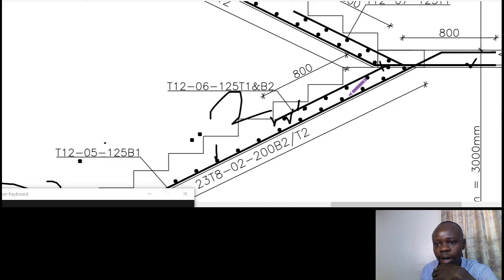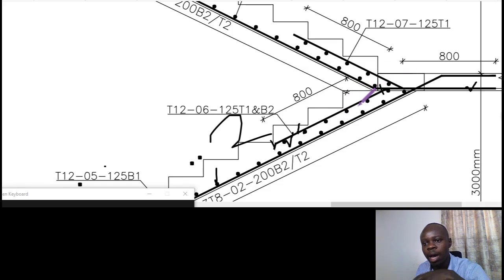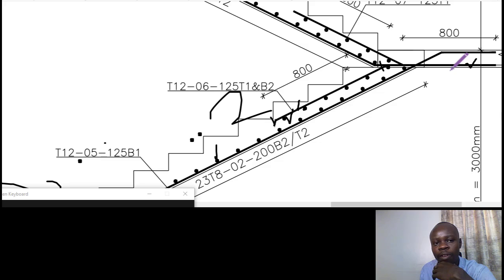You know that we have it like this now to the slab. Actually, these are at the slab level, but the additional weight of the reinforcement must be taken into consideration, and the reason being, even at the slab, you are not going to consider it the same as the reinforcement of the slab. This is dealt with as a staircase independently. So what we do, we've already indicated the other descriptions, so we are going to deal with it as one flight at the interval of 1.4 meter.